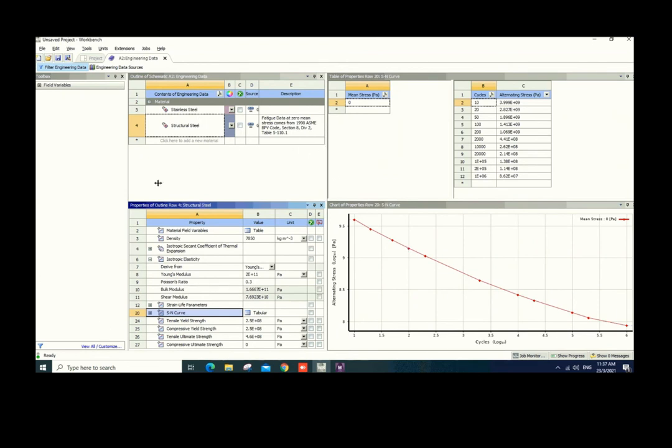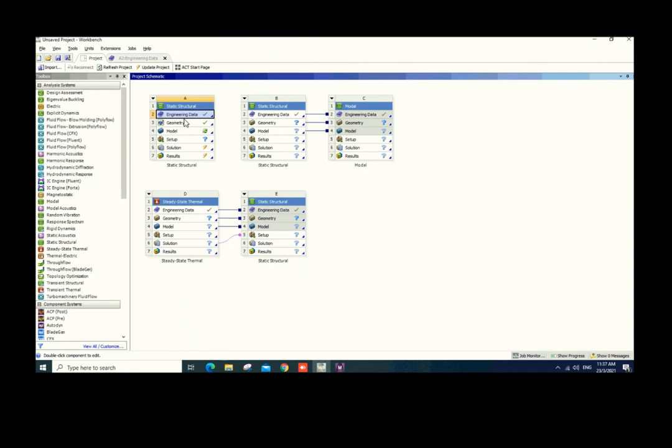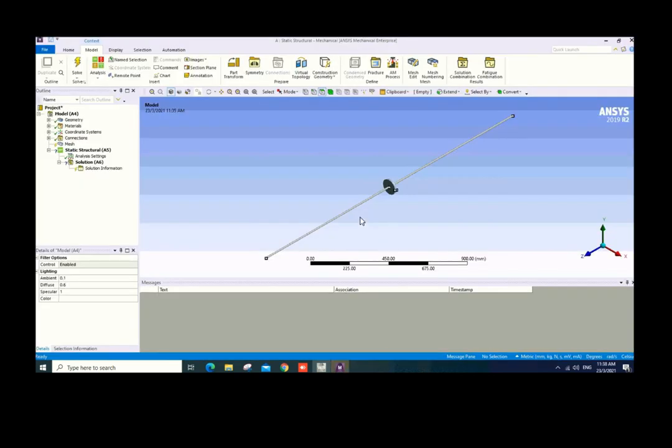These are the materials that you can set, and you can change according to your real materials. You can even create your own material properties. It's open under Workbench. Then you have the material, the geometry, and the model itself. Just now I clicked on materials, so you need an additional refresh again. Upstream data needs to be reread because I changed the engineering data a little bit, so you have to re-update and refresh everything.